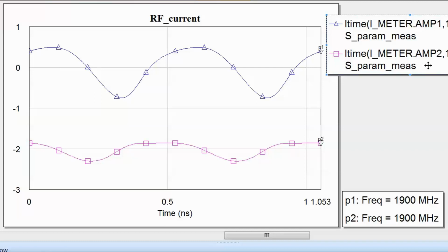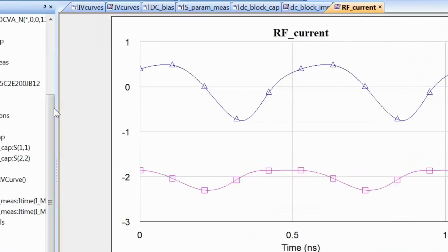Also, you can see that there is an appreciable quantity of current that goes back into our power supply. And so, well, we have to be careful with this, because this creates a considerable ripple in a DC current that should not have any RF ripple at all. And this would create havoc with our bias, and also may potentially destabilize our transistor and cause oscillations and all manner of problems. So let's have a look at the voltages as well.